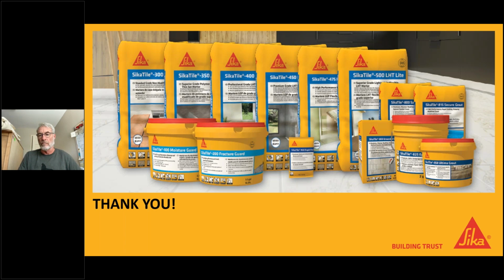In that situation, I actually wouldn't go with an epoxy. Epoxy's melting point, I could be wrong, somebody can correct me here, is typically around 300 degrees. We know it typically doesn't get that hot outside of a fireplace, but it could right around the edges. So an epoxy is something that I would stay away from, and I would go with a cementitious grout.